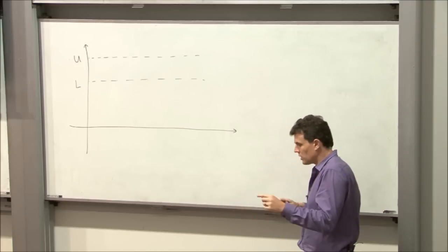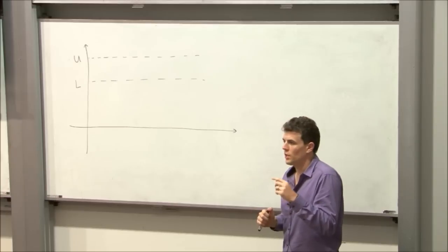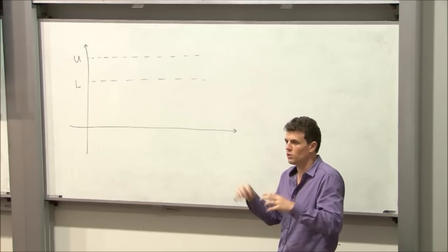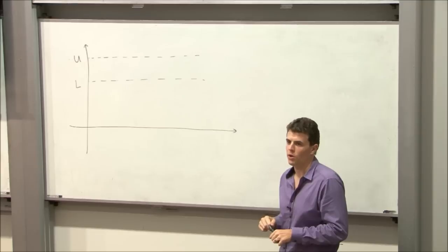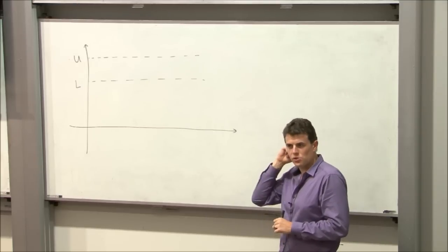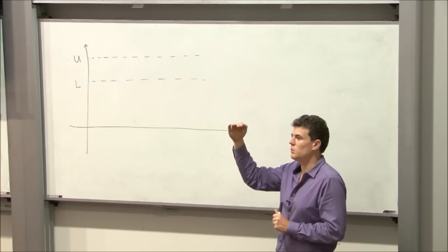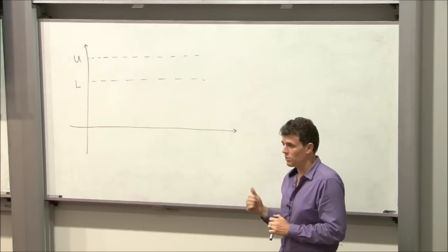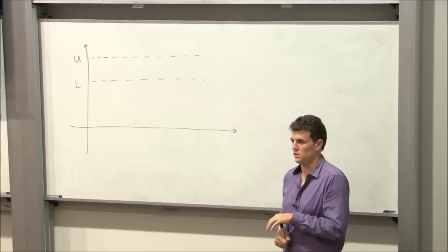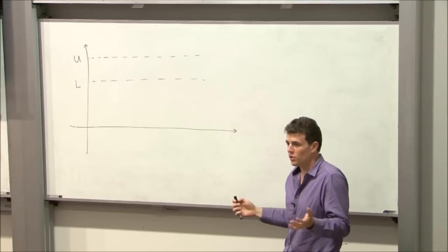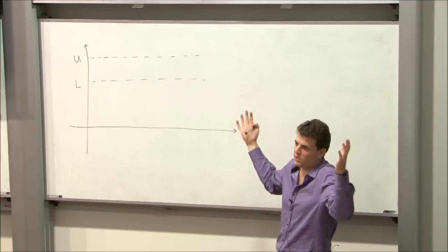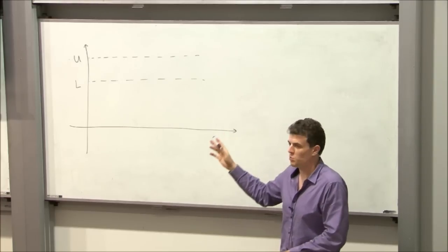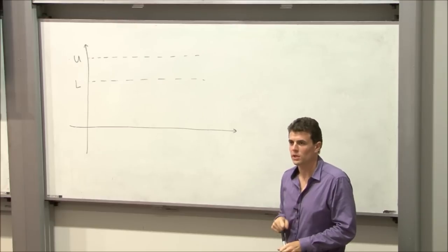And the regulations say at the limit load, there should be no permanent deformation to the aircraft. So no plastic damage, no yielding, nothing occurring at limit. Ultimate is an extra reserve. It's 1.5 times limit load that we put on top, and that the aircraft needs to, under the regulations, sustain ultimate load for 3 seconds. So it's allowed to have yielding, it's allowed to look like it's bent out of shape, but it has to survive and be able to land after experiencing ultimate load for 3 seconds.